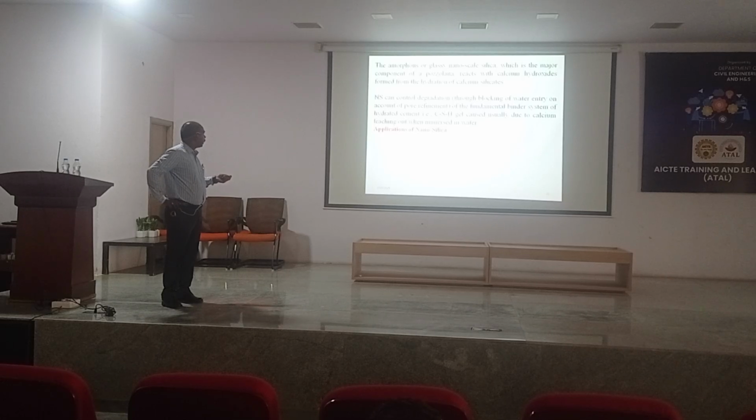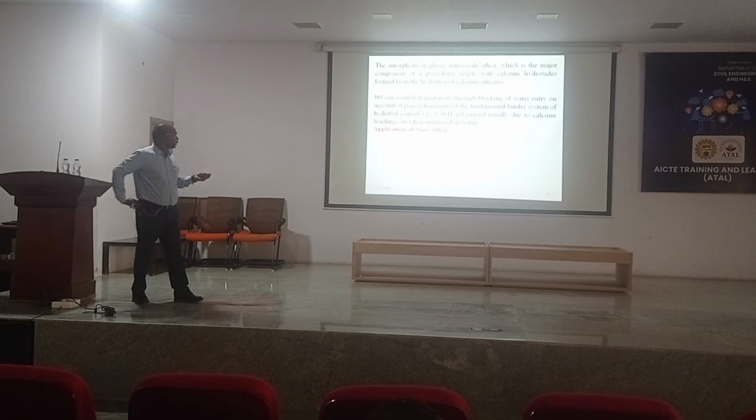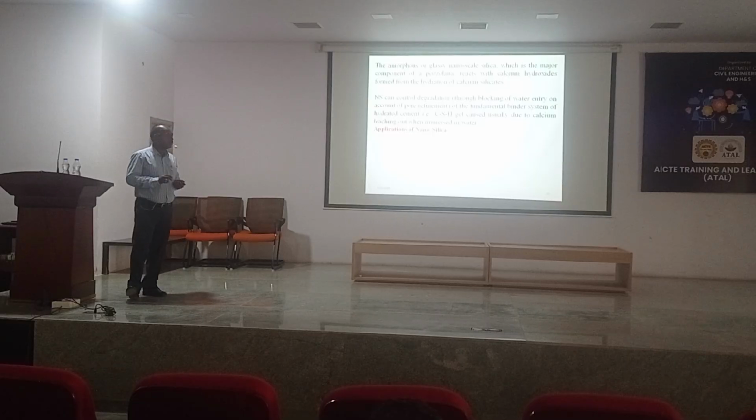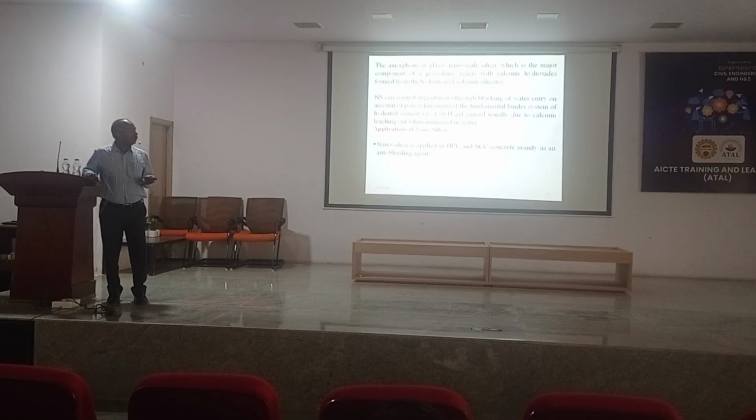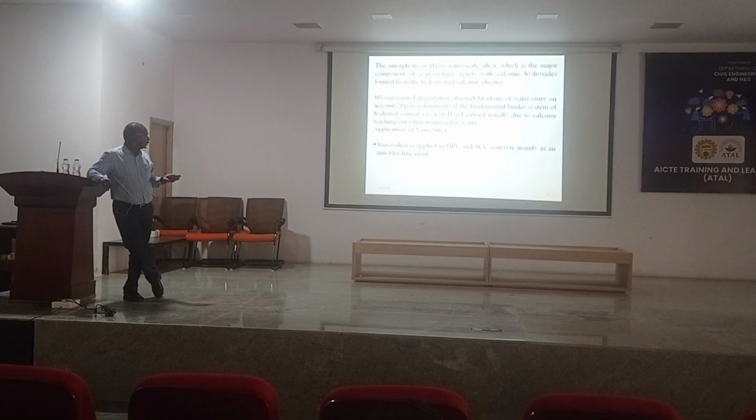Then the fundamental binder system of hydrated cement, that is CSH, is degraded usually due to calcium leaching. And applications of nanosilica are also very important. Nanosilica can be applied in high performance concrete as well as self-compacting concrete or any other. They can use it as an anti-bleeding agent. It can also increase the cohesiveness of concrete.